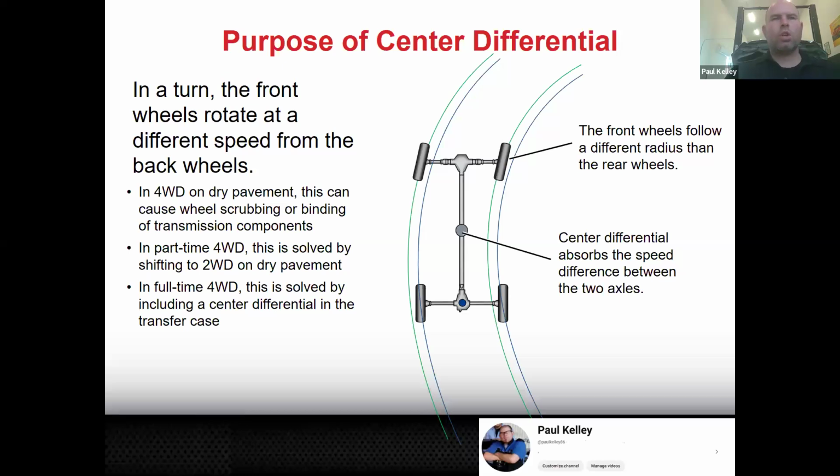However, your basic all-wheel drive system is all-wheel drive all the time, which means they're going to have to use a technology that's going to either have them constantly engaged, and you see now that's a problem for a center diff, or more than likely they're going to use something like a viscous coupling, which will basically decouple. It'll be free when you're just driving. And then if you start to slip, it will automatically lock up. And they can do it electronically and they can do it mechanically.